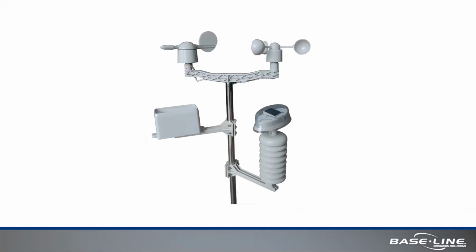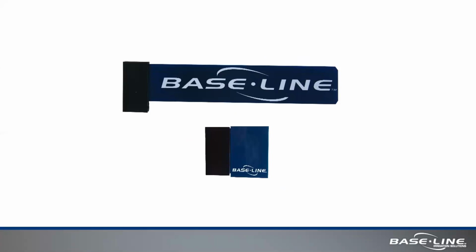Another would be using instrumentation, devices like a weather station, to get an environmental indication as to what's happening so that a controller can make a more educated decision in how much water it needs to apply. And then there's also subsurface sensor technology that can be utilized to get feedback or data from a site to help make irrigation decisions based on frequency of irrigation or duration of irrigation cycles.